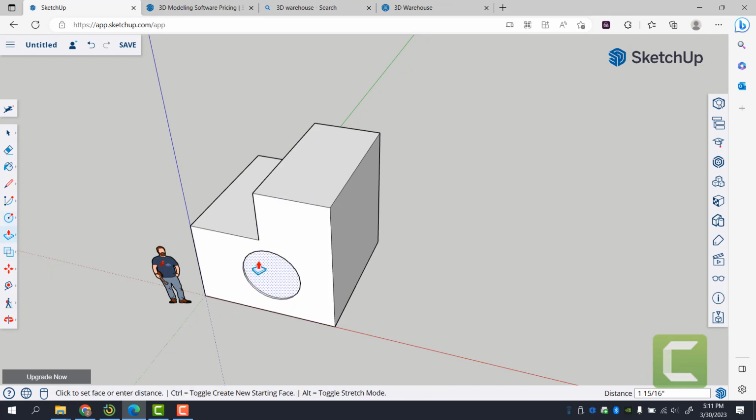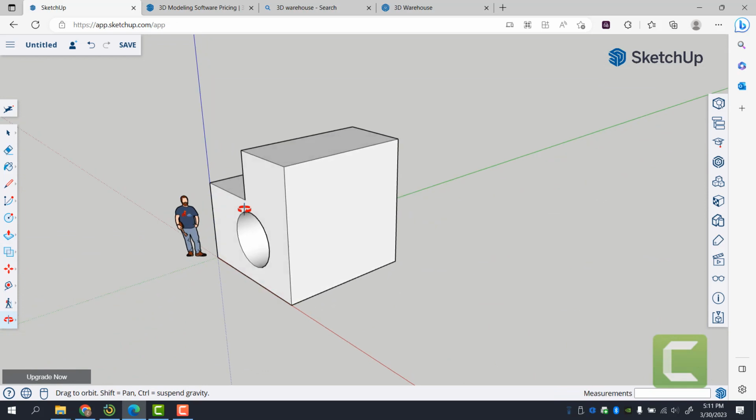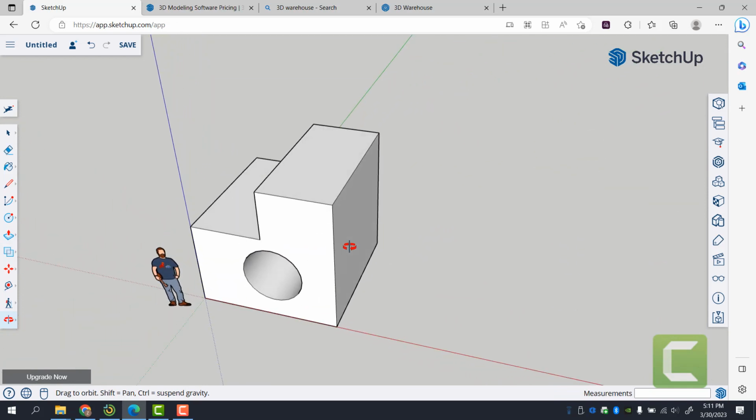One feature I do want to mention is if two surfaces meet while you're extruding, so let's say I'm extruding from here and I meet it on the back end, you're going to end up having the two surfaces go away and you have a void. It recognizes mass and void. Again, great for diagram study.